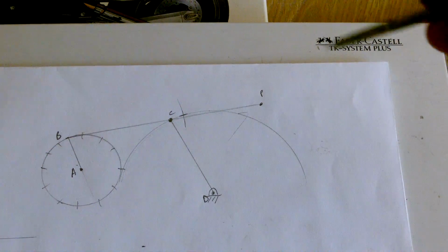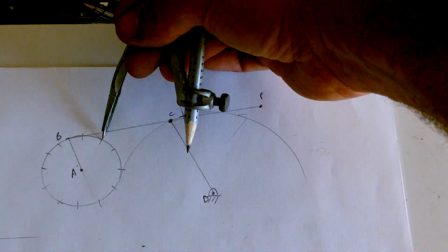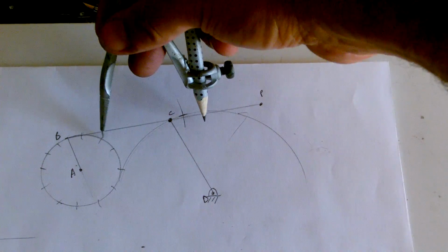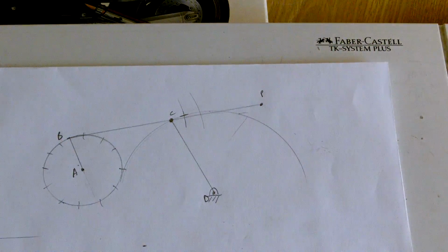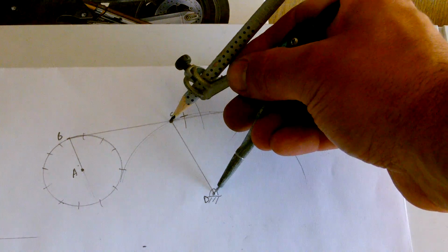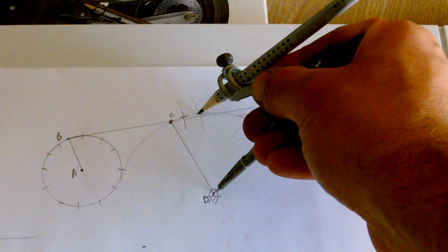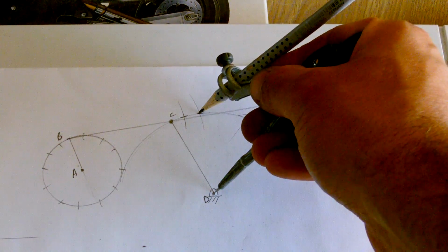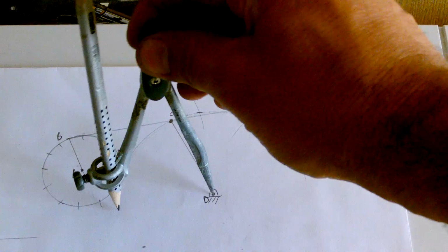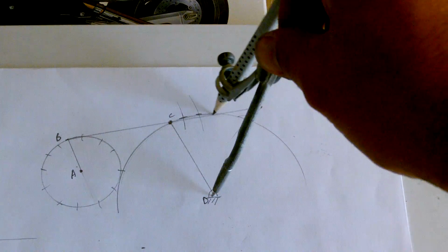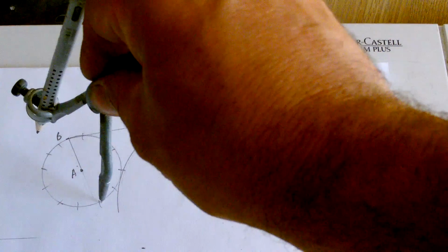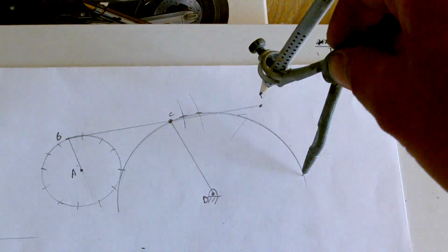So what you need to do is, from each point on the circle, mark BC, and from each of those marks intersect it with the same distance of CD. That's my new point. Since DC is always the fixed point, it's much better drawing that arc and then connecting each point from here to that arc.